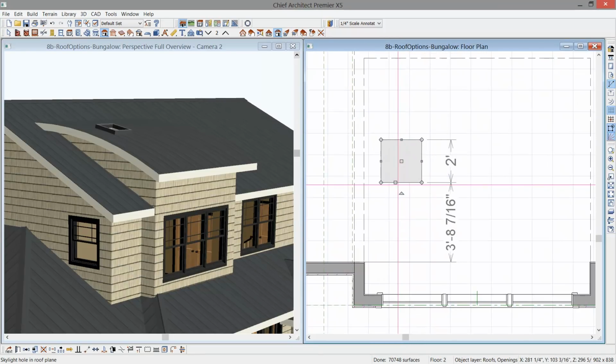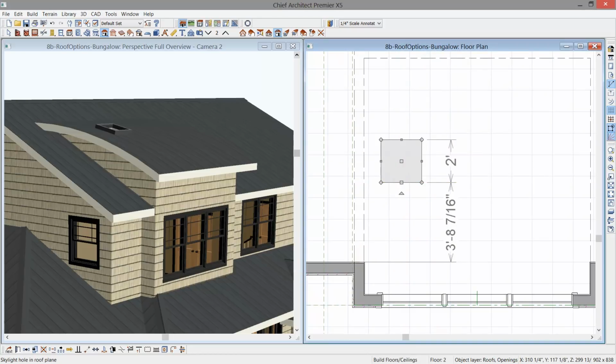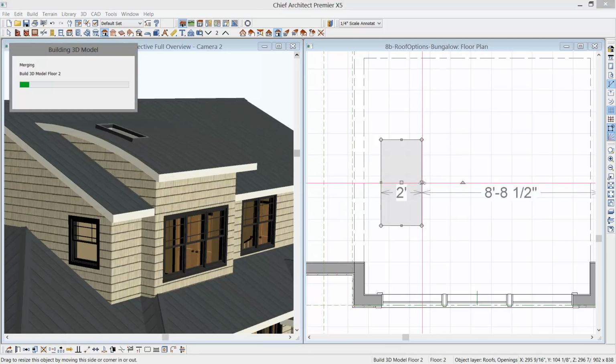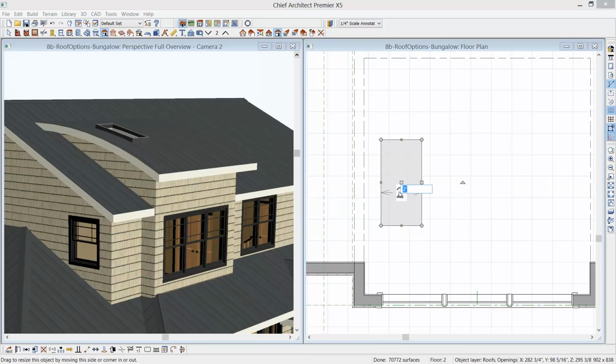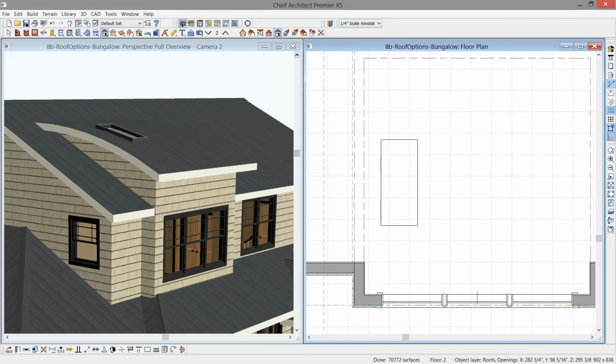And let's zoom in and let's go ahead and click on the dimension, make that maybe a 4 foot. And then on the other dimension, typically you might do your framing on 2 foot centers, so we can select that and maybe make it 21 and a half inches, depending on what the rough is. I'm not necessarily promoting that you put a skylight on this curved roof for water drainage, but I'm just going to show you how this works. So now I've got my first skylight.